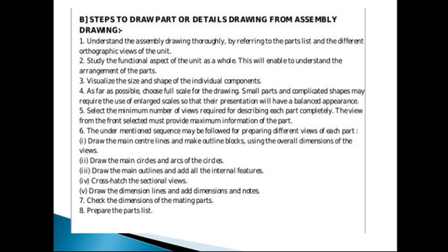So here we require to check some other views, like the top view. In the front view it looks like a rectangle, and in the top view it may also look like a rectangle, but if you see it in a side view, you will see a full circle, so we will understand that this is not actually a rectangle, it is a cylinder. So this kind of imagination power is required here.